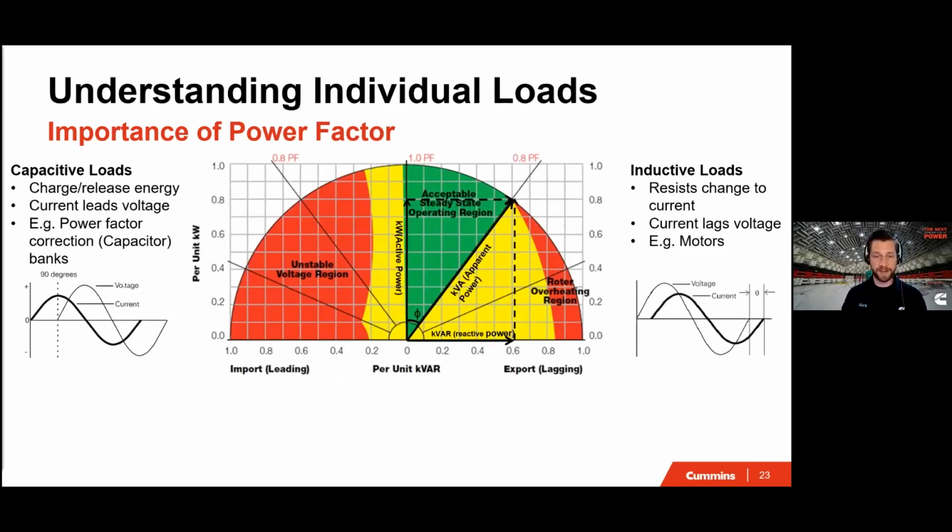So overlaying that same power triangle, just shrinking it down a little bit and putting it over this typical alternator reactive power capability curve. And if you haven't seen one of these before, I'll walk you through it. We can best outline the ramifications of straying too far outside of that sweet spot I just mentioned. Too far into the right side, where loads are too heavily inductive, we may see diminished power system performance as we are burning fuel to just merely create magnetic fields, as opposed to doing some real work like driving a shaft. Now, understandably, when a motor is first starting, the power factor will be here for a moment.